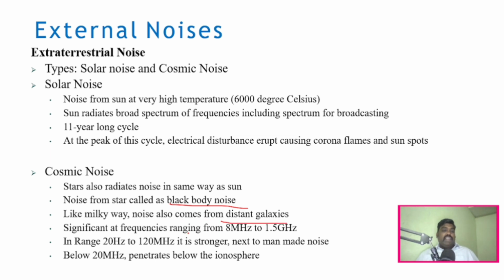And these noises are significant in the frequency range from 8 megahertz to 1.5 gigahertz. In the range of 20 megahertz to 120 megahertz, it is stronger, next to man-made noise. And below 20 megahertz, it penetrates below the ionosphere. Right? These are some properties of this cosmic noise.